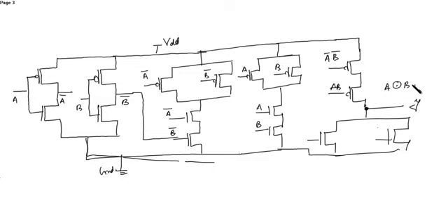So now you can see it's too complicated to draw the twisted schematic of this and then the layout. So what we will do, we'll draw the layout from the schematic by using the transmission gate. Let's see in what way you can reduce the number of PMOS and NMOS. This can be done by drawing the schematic, keeping in mind the truth table of the XNOR gate. So you can write it as schematic from truth table.